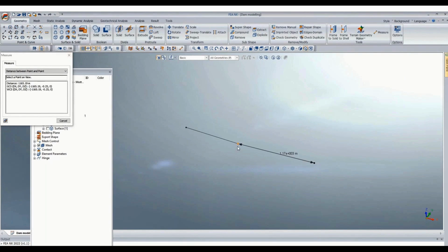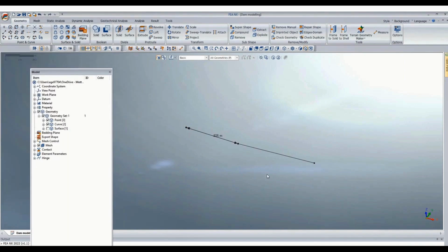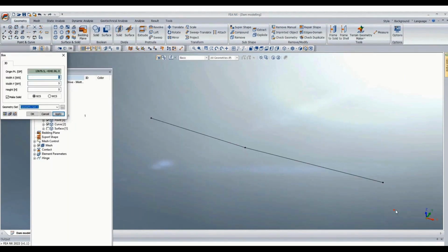Okay, and this length is 824, so 1200 meter. I'll create one box here. In the next direction, 1200, width say 100 meters, 150 meters, some arbitrary number so that it exceeds the base width of the dam. So it can be an arbitrarily large number, 150 at the initial point, and height is 293 was the top. Keep 293. Okay, and let's place it here.